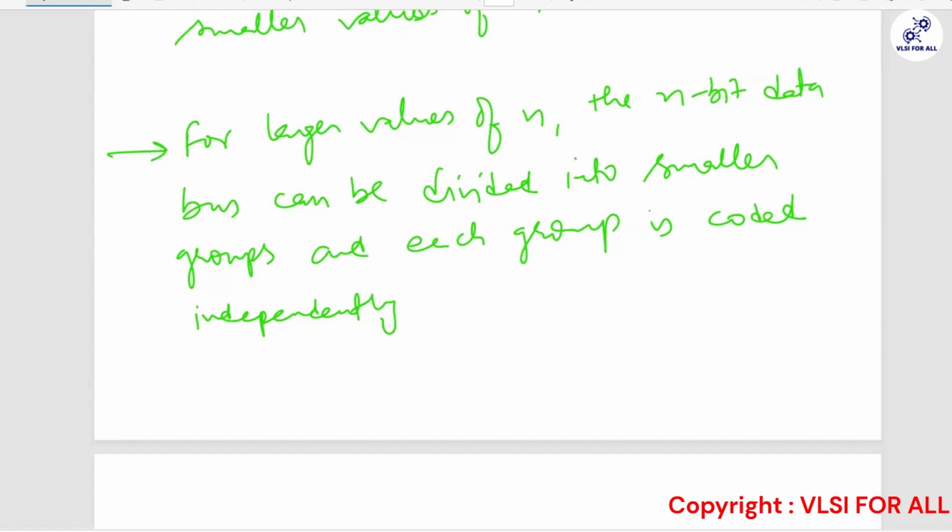If you somehow restrict the clock from toggling, you get one of the most successful ways to restrict switching power. That is one of the most commonly used power techniques, because the major component of processor power is clock power, as it is switching 50% of the time.